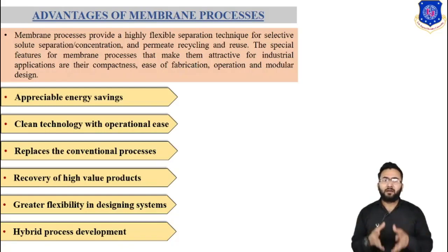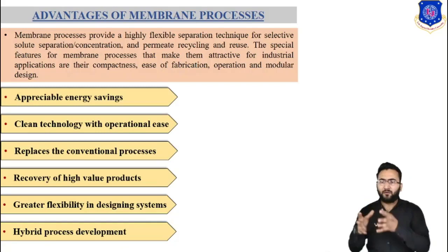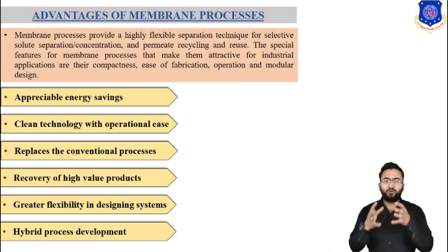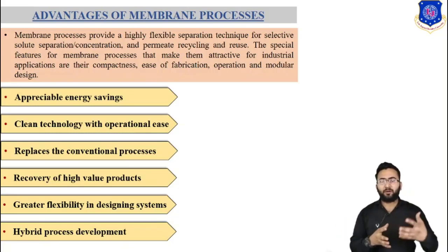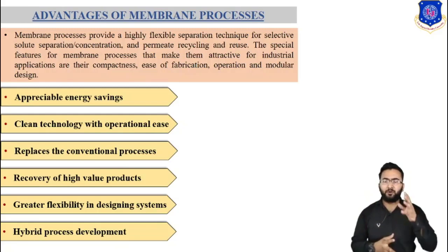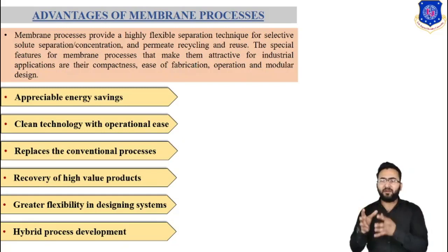For example, dehydration of organic solvents is done mostly by distillation. A membrane module can very selectively separate water from many organic liquids, including alcohol. Replacing the whole distillation column might be very costly. It is more advantageous to use both the distillation and the membrane unit combined in series operation. The hybrid can successfully increase the capacity of an existing plant and improve product quality. A hybrid process is successful if overall cost and performance are an improvement over the individual alternatives.